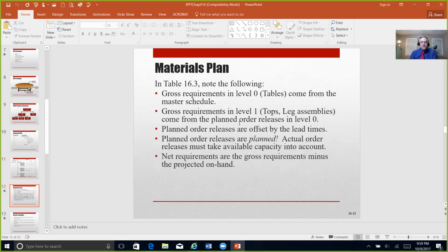So this example really is about this time-phased materials plan on page 413, where we have all the purchase orders and all the shop orders, which are integrated to provide the materials when they're needed at the right place and time in the assembly, in the manufacturing process. And we manage these lead times so that we can meet the planned lead times where there are no unnecessary inventory accumulations, or in other words, we don't waste time waiting for materials on the shop floor.